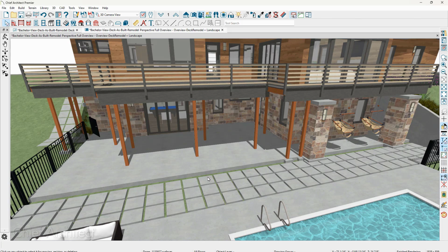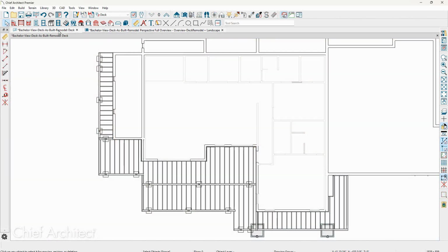Now, as I begin adjusting the framing, I typically won't do this until the dimensions for the deck are good, because I want to take advantage of the program's automatic framing. Let's begin with the framing component of this, and let's go back over into the floor plan view here. Now, the first thing I'm going to do in cleaning up the deck framing, I'm going to remove all the foundation and post supports that the program put in. I'm going to select one of the foundations and its post.